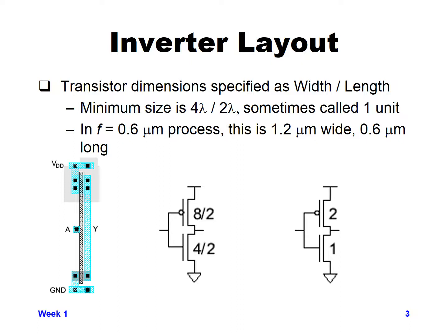in terms of mobility, the PMOS mobility was half as much as the NMOS mobility. And so if you wanted to have equal drive strength of your NMOS and PMOS devices, you would have to make your PMOS device twice as wide as your NMOS device to keep approximately the same drive strength. And so that's why you'll see throughout a lot of the circuits, the PMOS will be twice the width of